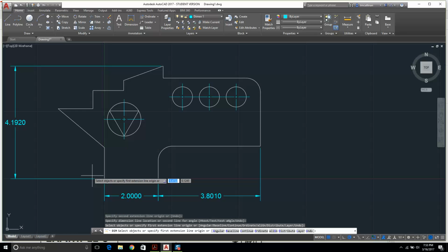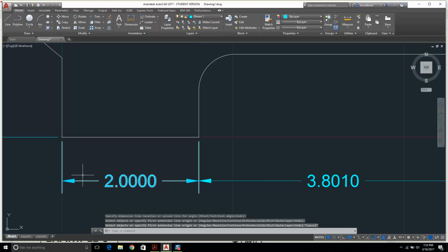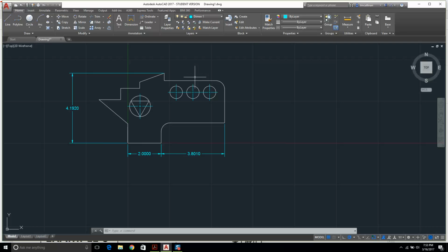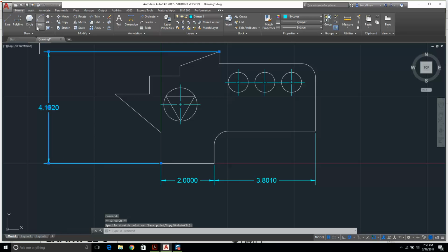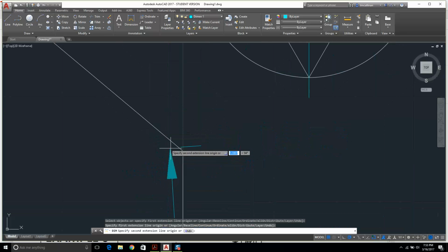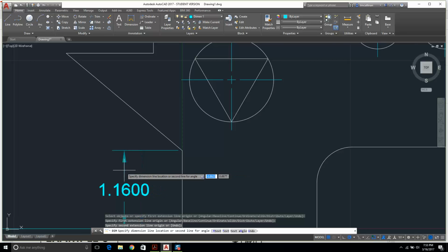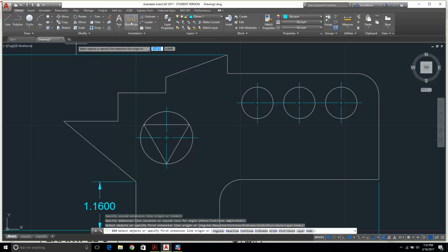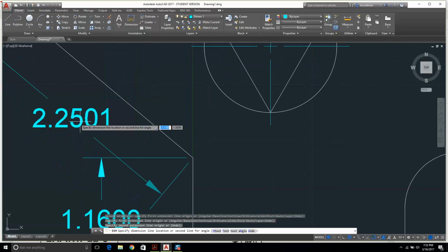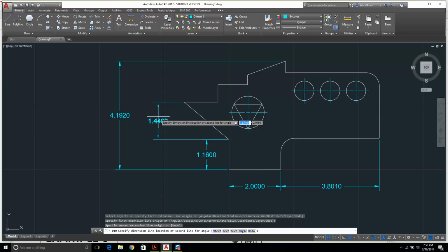Do you remember what the lines of dimension are called? This is the dimension line. These are your dimension arrows. These are your extension lines. Your extension lines should not touch the object or really cross over it. The bigger dimension goes to the outside. You'd be crossing if you did that. Come on now, there we go.